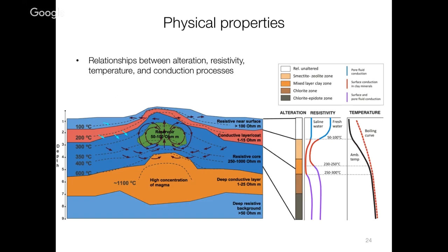this. Up until recently, I think what people were primarily looking for was a situation where you had a near-surface resistor, then a conductor, then a resistive region, and then a deep conductor. So almost like a 4-layer model. What they're interested in is the base of this conductive layer, because nothing is going to happen right in the clay zone, but beneath here there might be something.